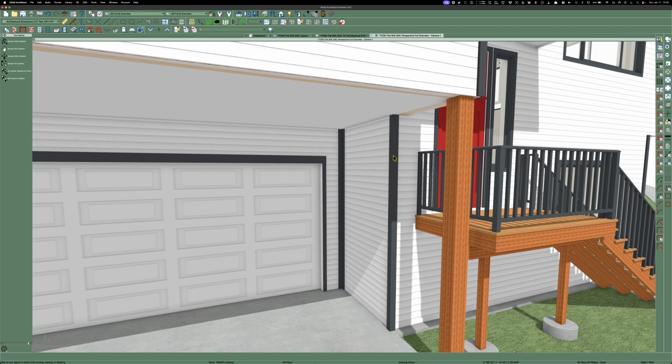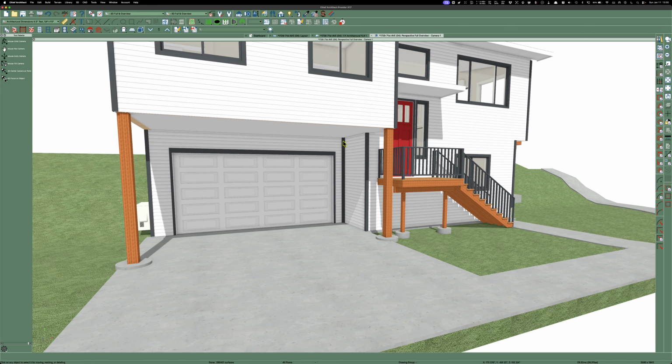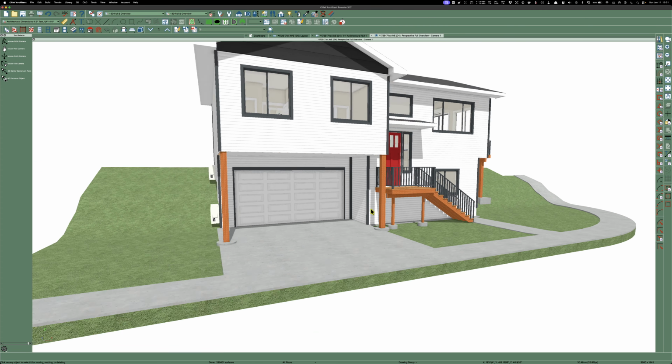And you just take a 5/4 and rip it so that it's a 1 inch by 1 inch corner board piece, or whatever trim you're using. And you fasten it to the inside frame, well, the plywood of the framing, and then you butt your siding into it, and you caulk as you go each row. So it's not so proud. It's a nice, clean, thin little board.